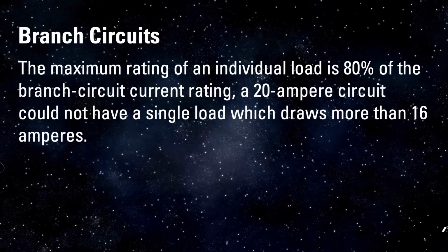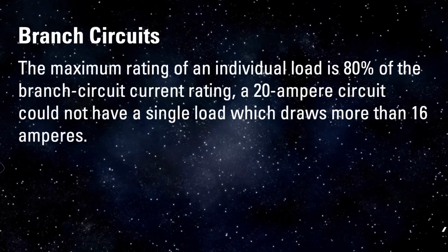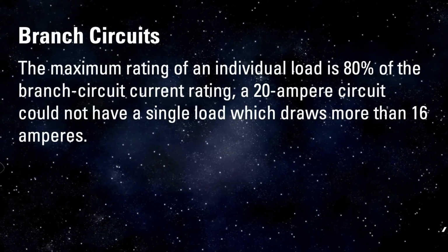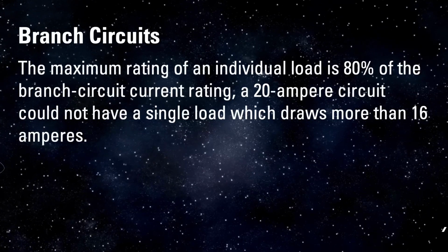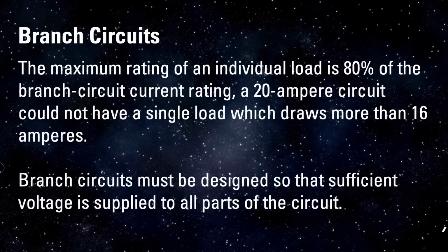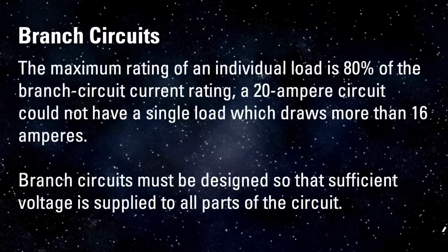The maximum rating of an individual load is 80% of the branch circuit current rating. A 20 ampere circuit could not have a single load which draws more than 16 amperes. Branch circuits must be designed so that sufficient voltage is supplied to all parts of the circuit.